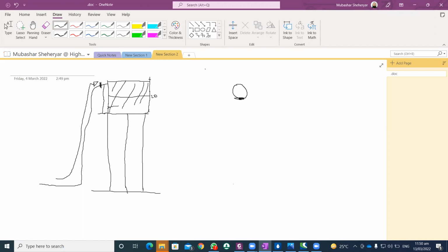20 feet from the base, then the inlet valve should keep itself active and start closing. And when it reaches, for example, 25 feet, it becomes fully closed, in order to prevent the flow from the tank through this valve. The tank is always draining at the outlet provided at the bottom in order to provide water for the water supply system.